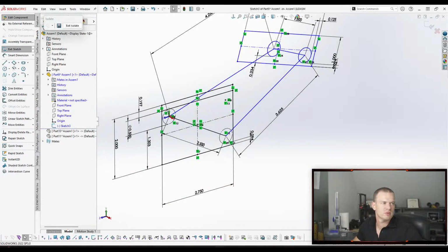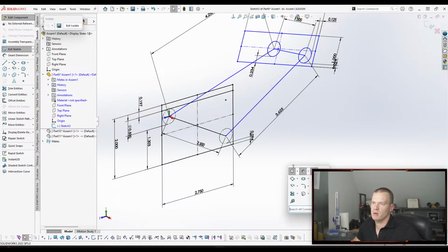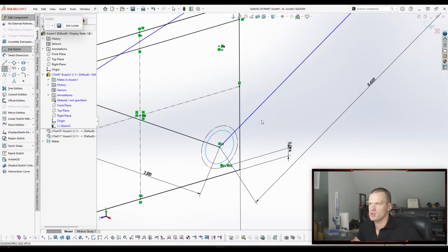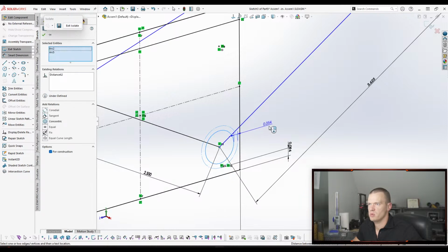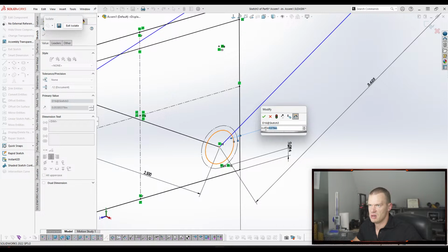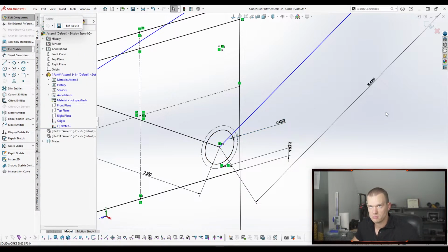All right. So like I was saying, the simple solution would be you simply add sketch geometry that controls your gap, right? So now we can make a relationship between the hole and our pin diameter, and we can say, all right, we want the gap to be 50 thousandths, because we're going to 3D print it.